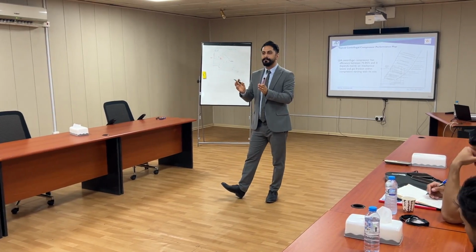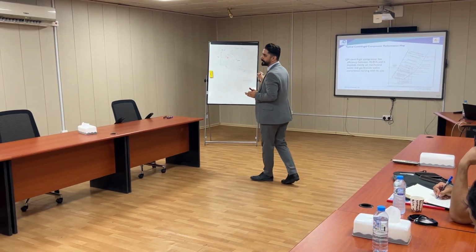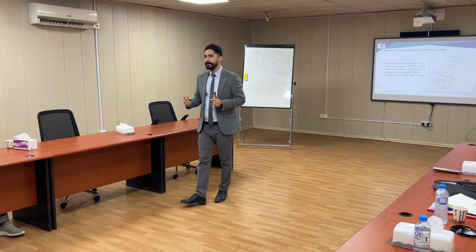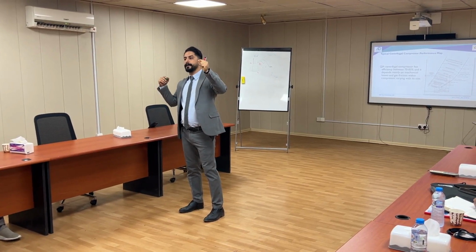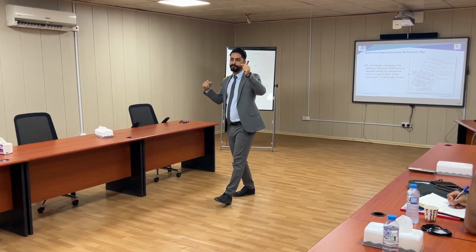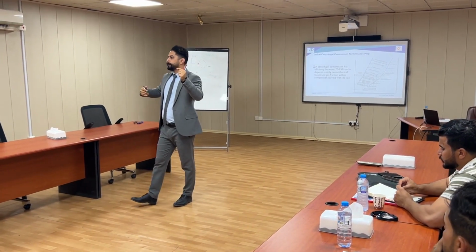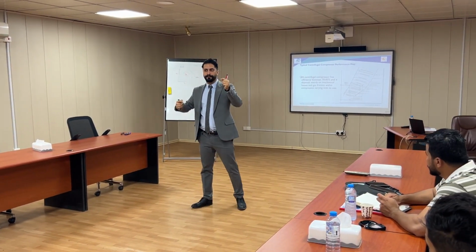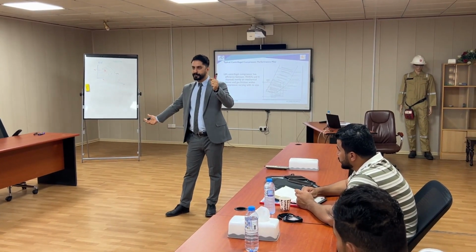If some void area is between the impellers, it reaches a point where the discharge pressure is going to be higher than the pressure in the impellers. Why? Because the impellers are not able to impart energy to the gas molecules. We said that in centrifugal compressors, firstly we increase the velocity, then we change it to pressure.